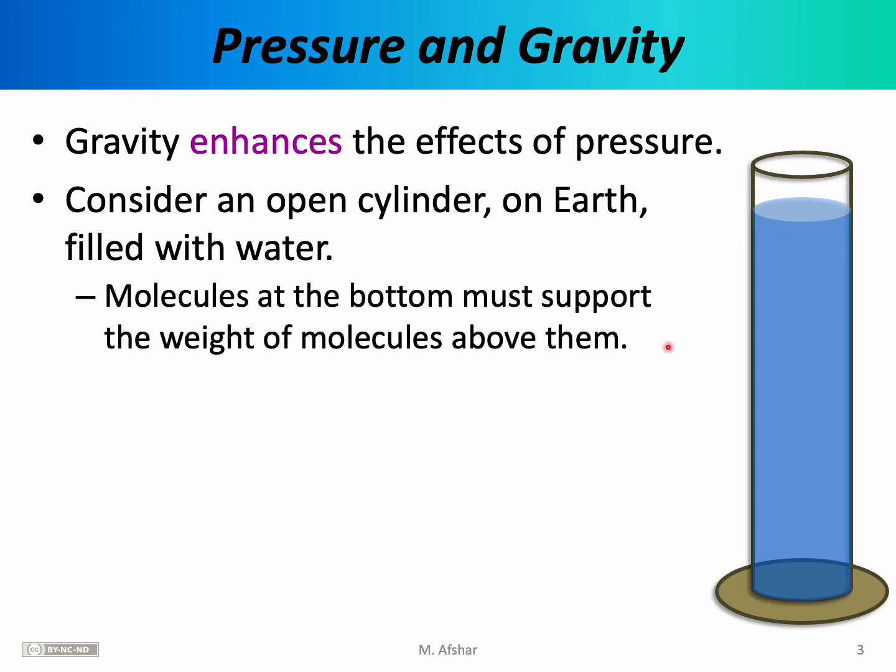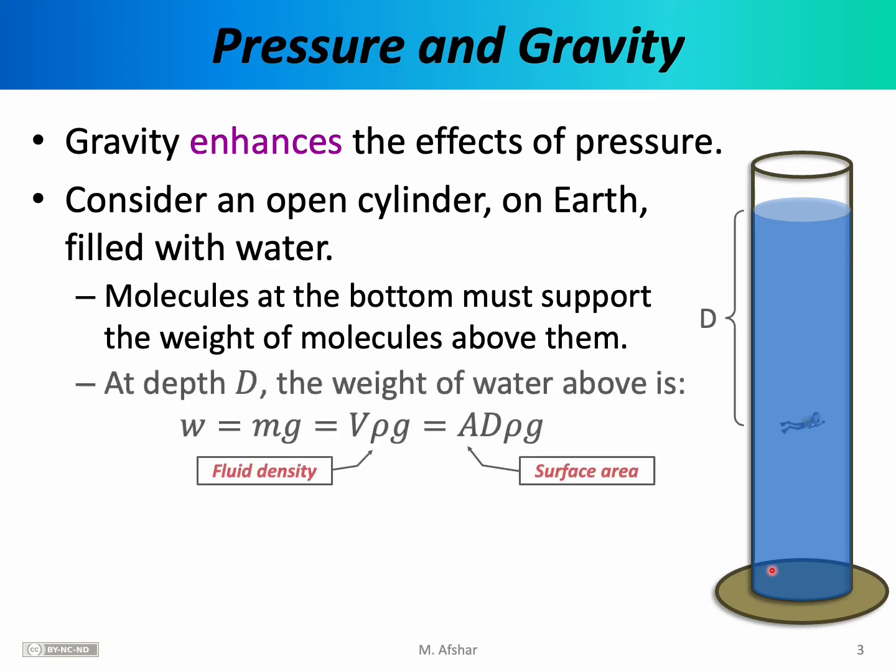This is important because pressure is force divided by area. And the force we're talking about here is the force of gravity or the weight of the fluid. If the weight or the force increases with increasing depth, then the pressure should also increase as we go deeper inside the fluid. To make that more precise, let's consider a specific depth d. So consider a molecule, for example, swimming around inside the container at some depth d. What's the weight of all of the water that is above that molecule?